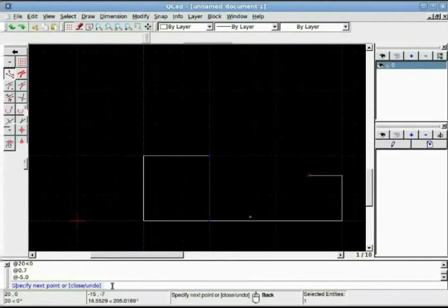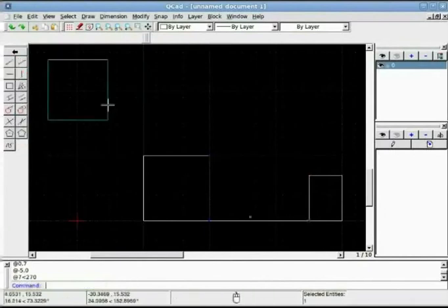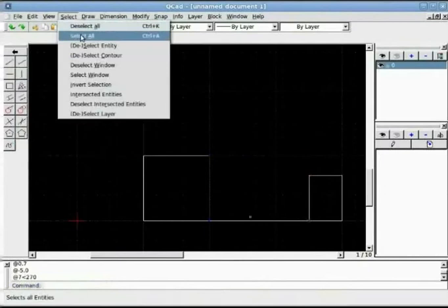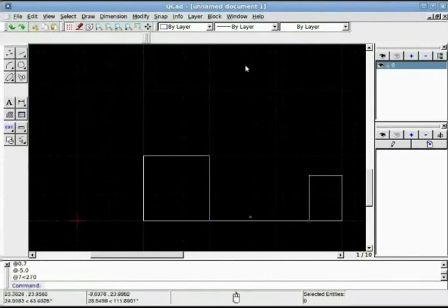Once I know all the different methods I can draw objects with, I can use combination of any to draw objects. So now to draw that vertical line, I can use polar method, relative polar. So I say at, I know distance is 7, I use angle symbol. Since it is 6 o'clock direction, it is going to be 270, and this completes our drawing. So this is how you use different methods in the QCAD.